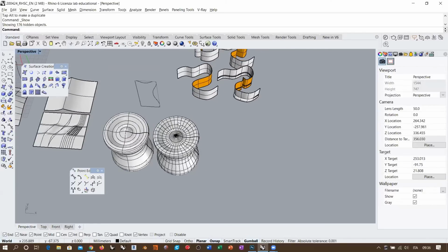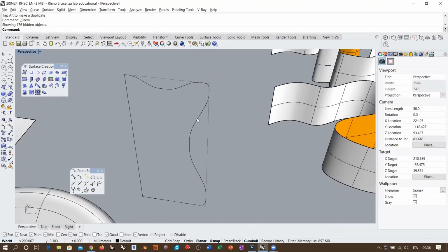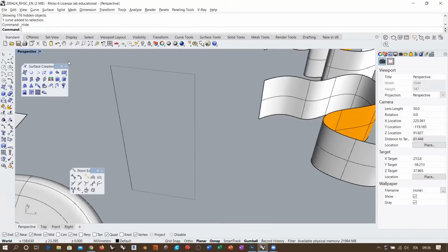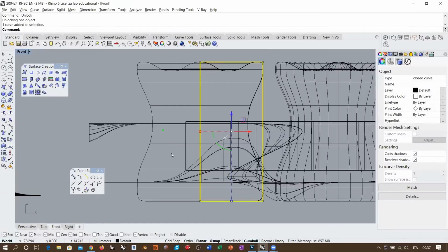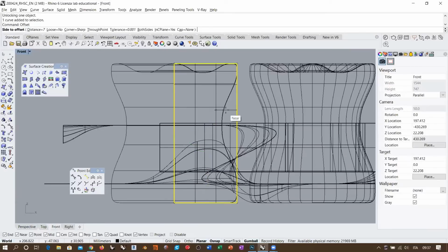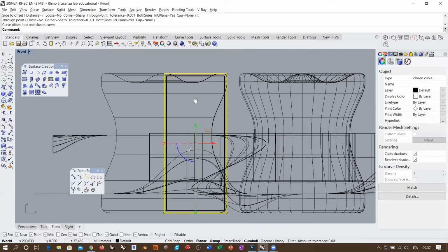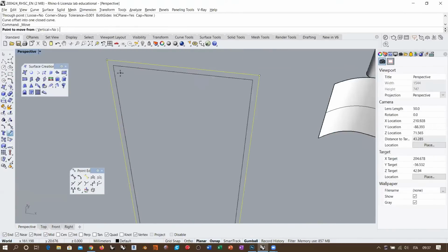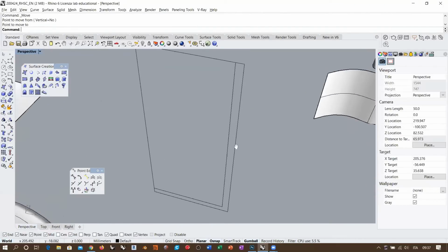So for example, if I want to produce some kind of particular deformation in a glass, let's try and draw a glass. In order to draw a glass, eventually I would also need some thickness for this object. So I'm going to go to the front view and offset this thing with a through point, so I can give a very small thickness initially. Then I will take this rectangle and move it so that this vertex is here. I need this as a reference set of curves.